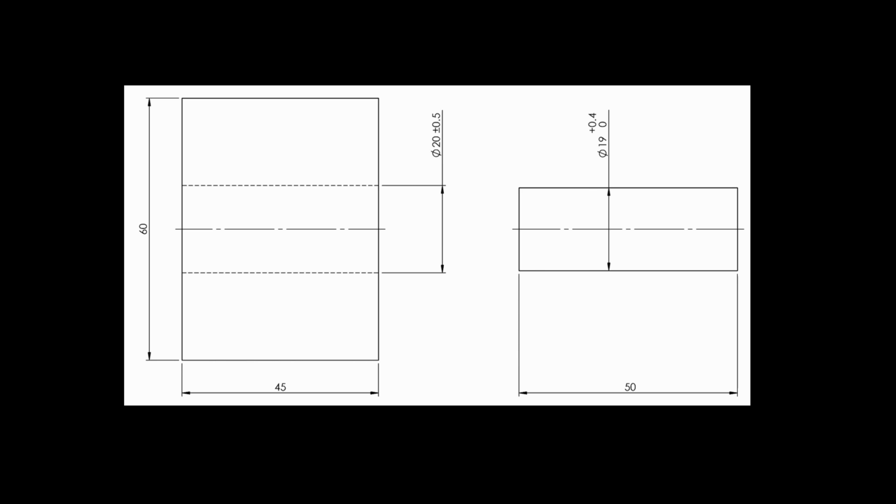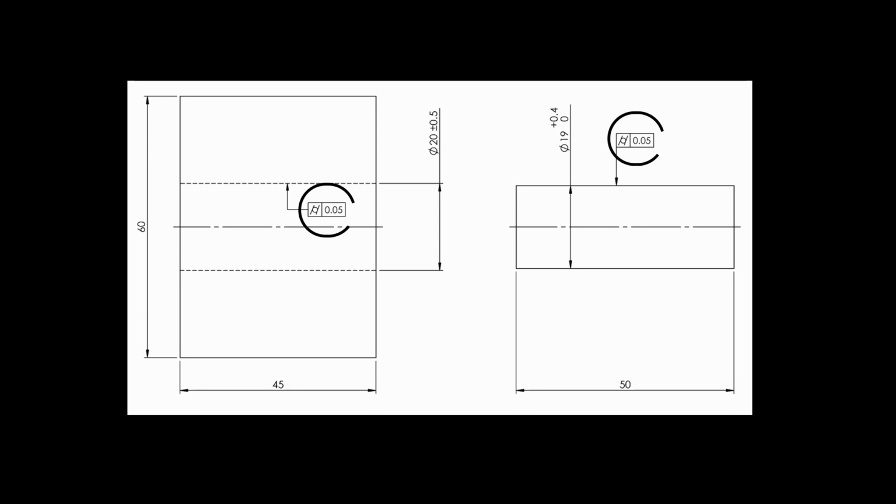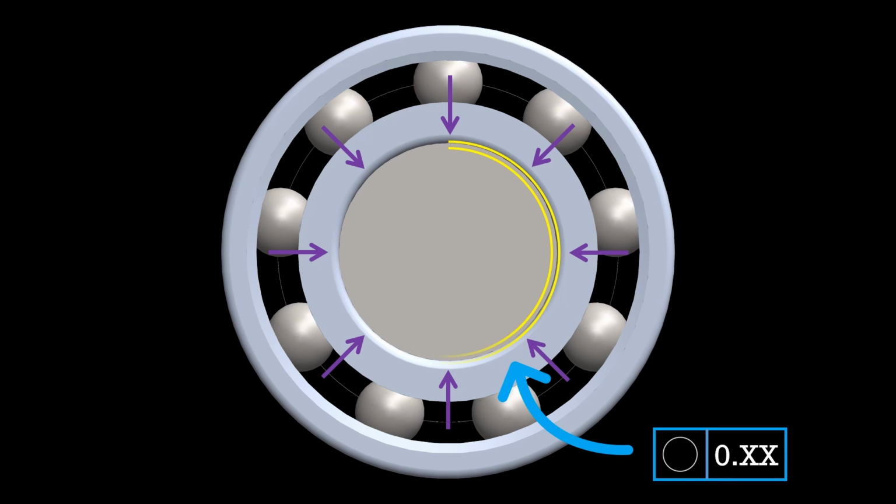If you do not apply any geometrical form, the form will be within its size limit because that is GD&T Rule 1. Apply the geometrical form control only if you need a more precise form than its size limit, its tolerance limit. Like cylindricity form control over a bearing shaft. I hope you got my point.